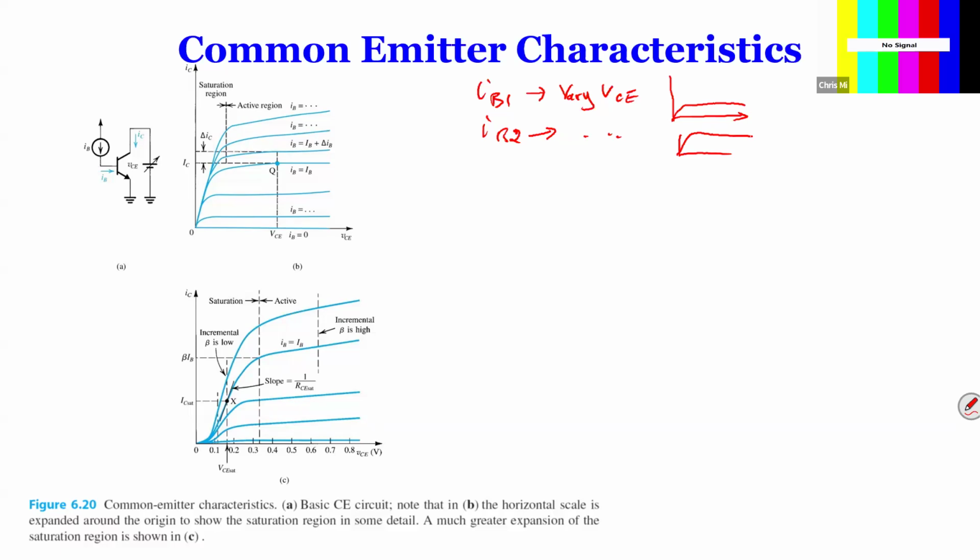What this graph tells us is that when you want to operate this as an amplifier, you want to be in this middle region. You don't want to be too close to here because it might jump into saturation. Even at just a little bit above, say 0.3, even though you are in the linear region, a little change in the amplitude of the input might push you into the saturation region, and your system will become nonlinear.